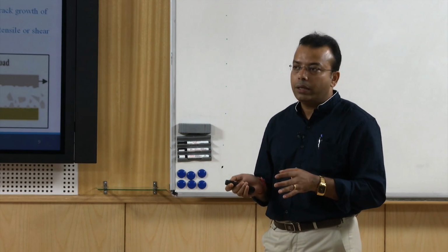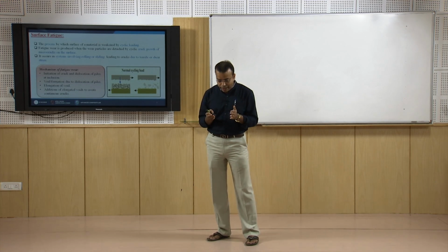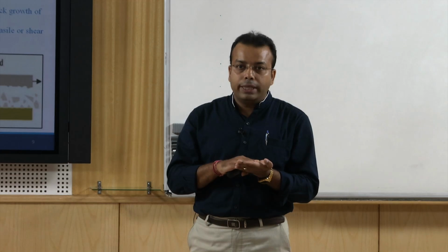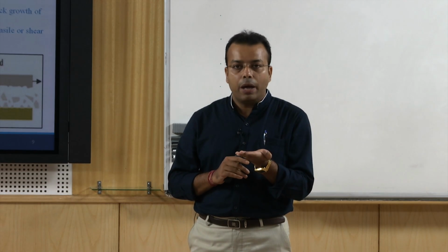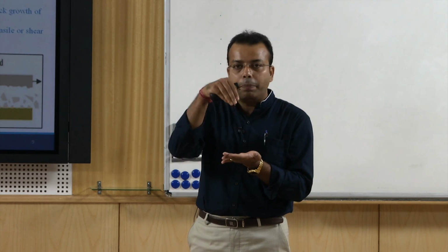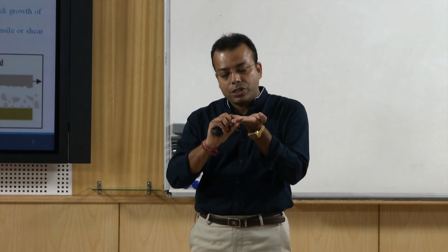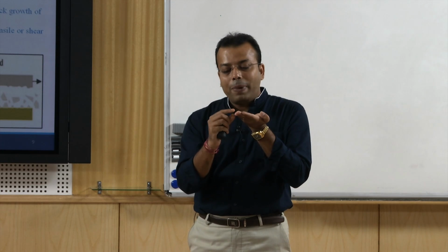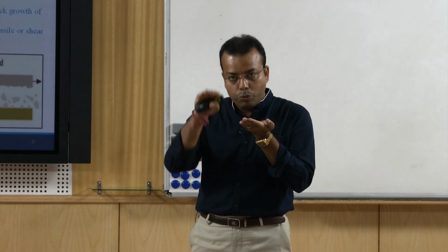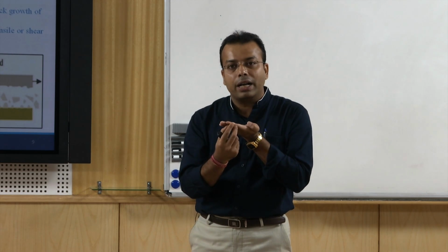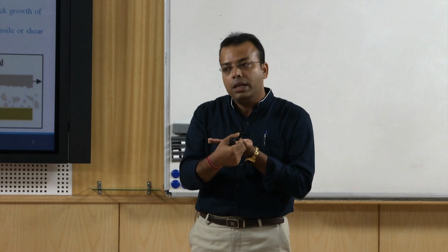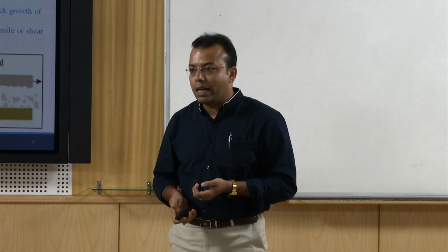From the name itself you can understand that surface fatigue depends only upon the load, that means the normal load. Suppose you have a surface and you continuously apply pressure or load to that surface. Initially plastic deformation will take place, that means the elastic properties of that body will go down, then the surface will become harder, but if you still give the constant load, after a certain time that surface will fail. That is known as the surface fatigue.